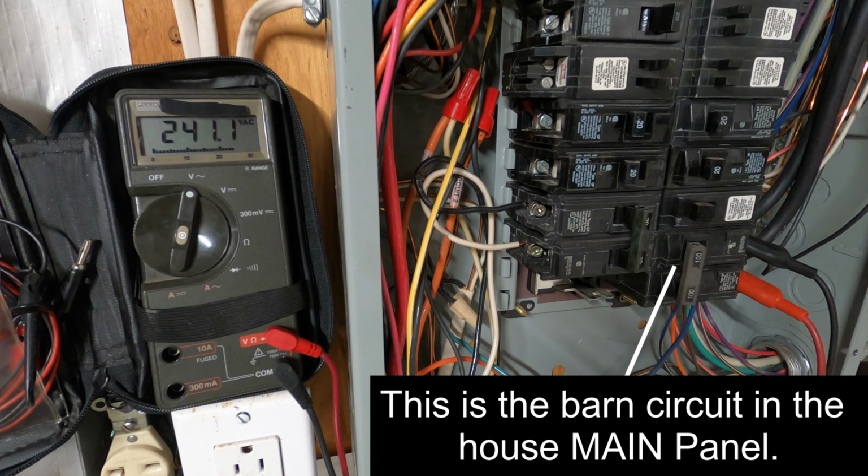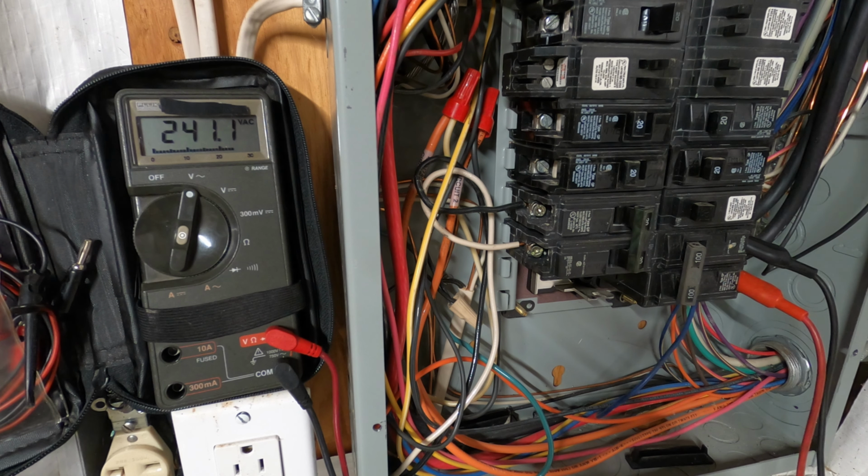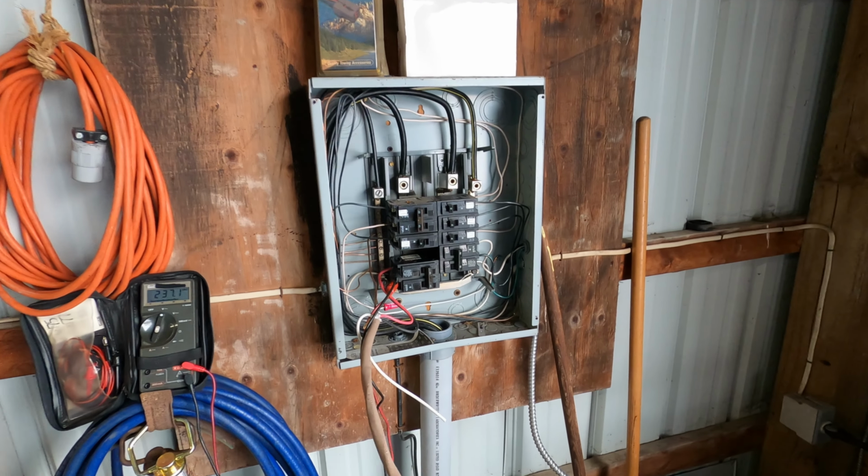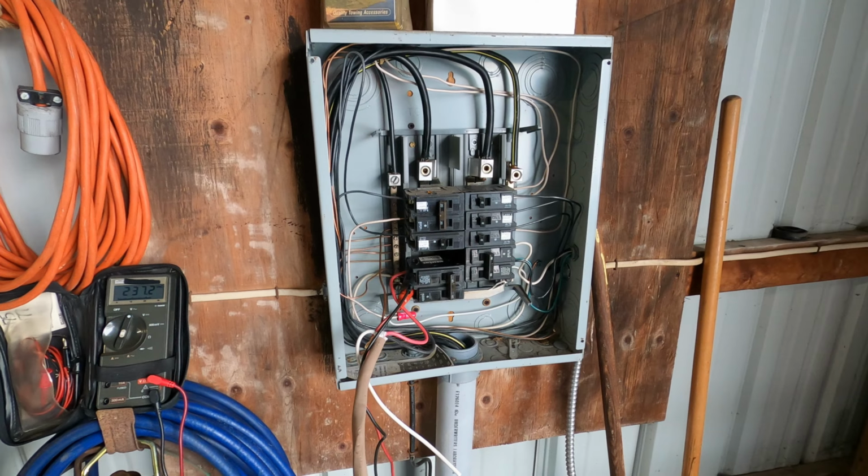For the next voltage drop test, I started by hooking my voltmeter to the barn feeder circuit breaker in the main panel. It starts out at 241 plus volts, but we'll see it drop when the water heater load is turned on, down at the barn sub panel. So here's the setup.